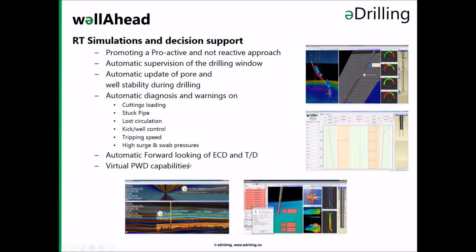The system also gives, as I mentioned previously, automatic look-ahead of ECD and of the torque and drag. And the calculated pressures are de facto a virtual PWD, since these models calculate the pressure profile in the whole wellbore at any time in the operation. Also, when you don't have any sensors functioning.